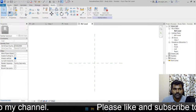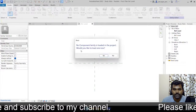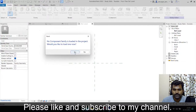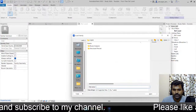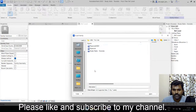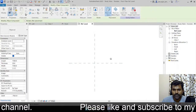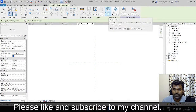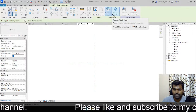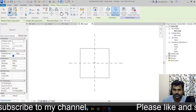Okay, just go to create component, and here there is no component family loaded. Let's load. Go to desktop, here table YouTube plywood family, and open. Now you can see for the placement I have 2 options. I can place it on the face, otherwise I can place it on the work plane. Select place on work plane, okay, and just place here.